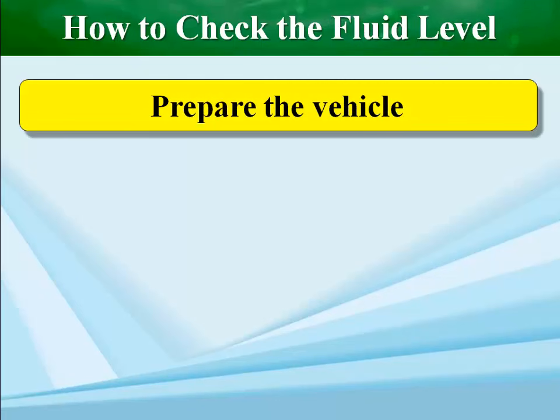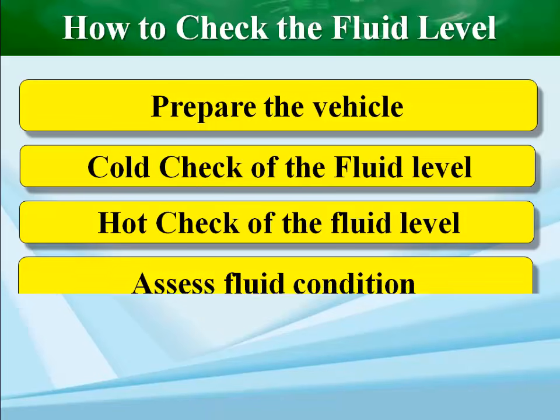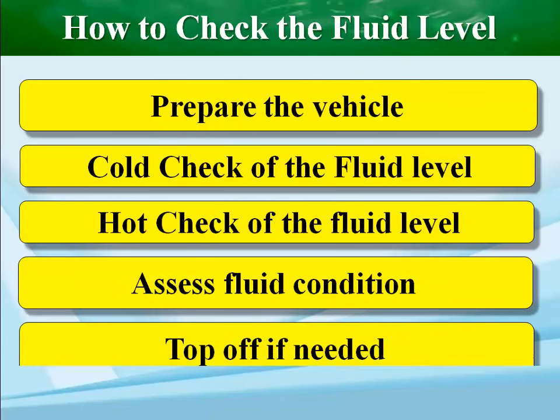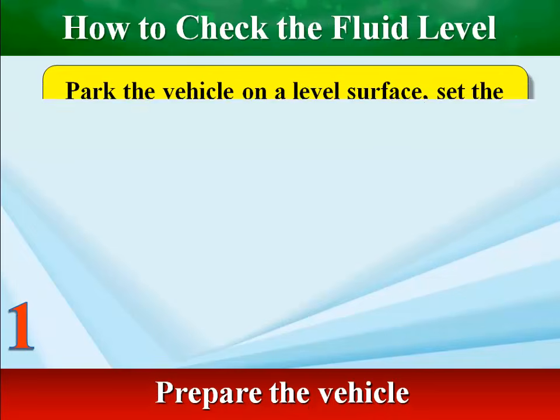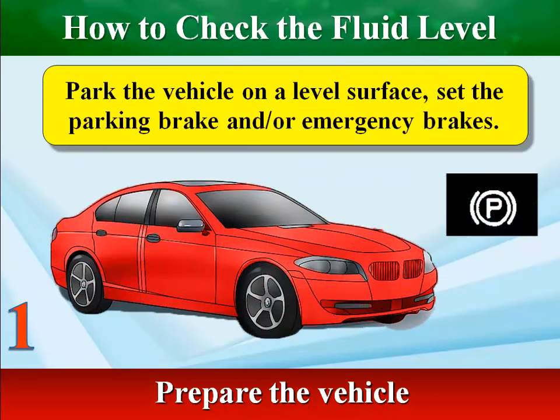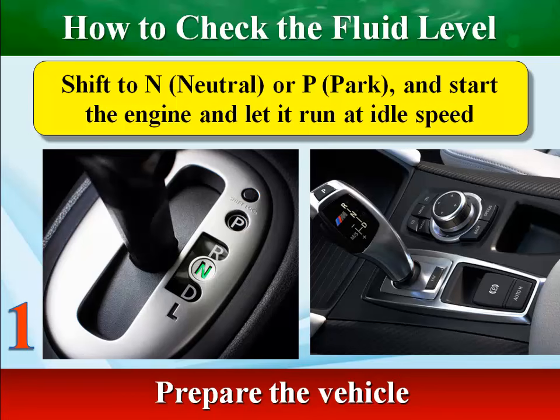Check the fluid level using the following procedures. Park the vehicle on a level surface, set the parking brake, and/or emergency brakes. Shift to N, neutral, or P, park, start the engine, and let it run at idle speed.